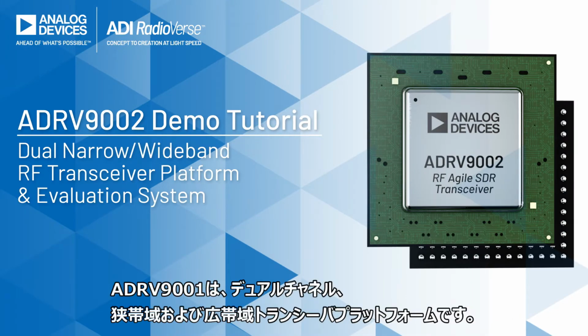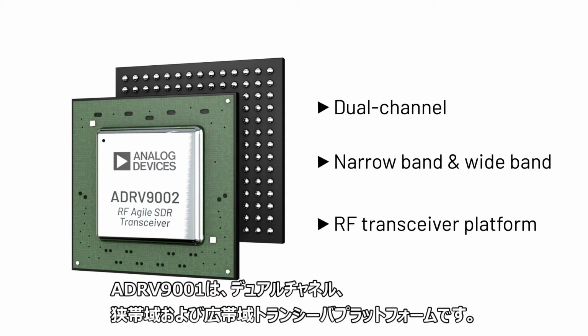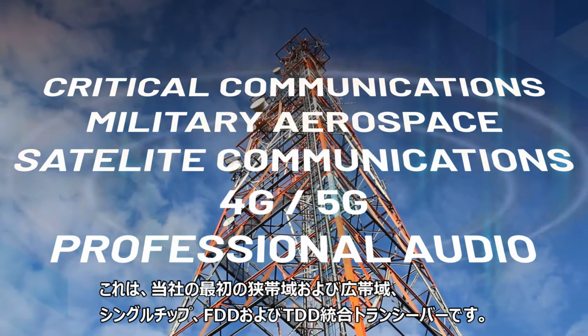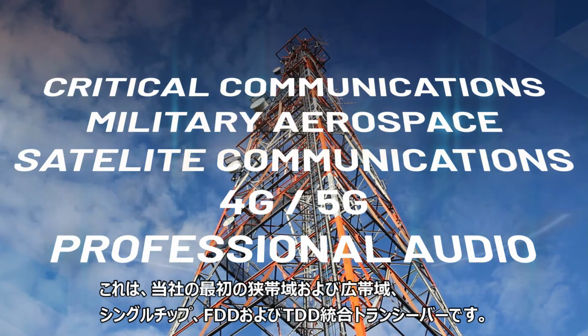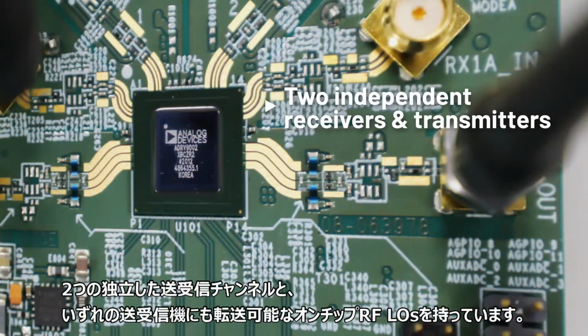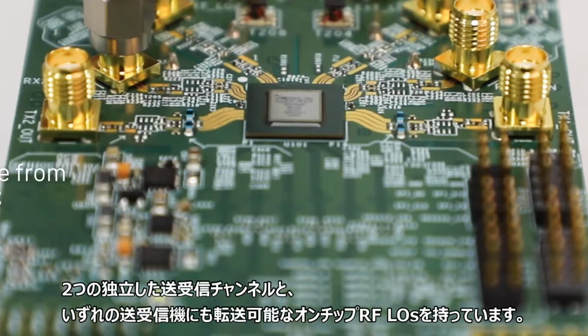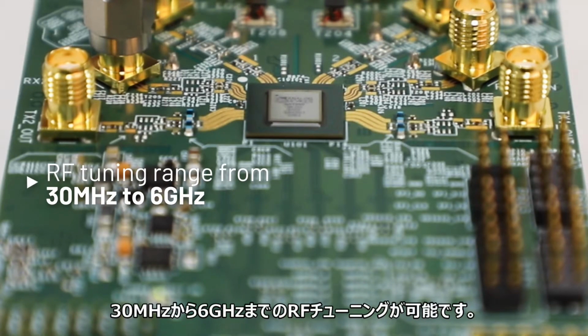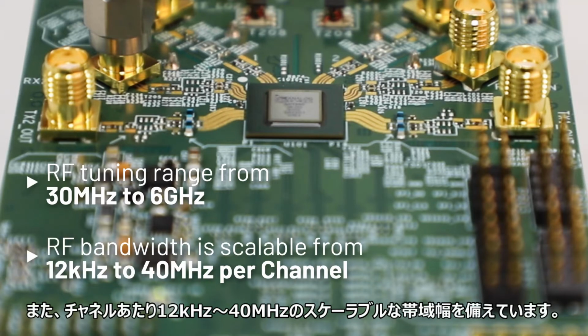The ADRV9002 is a dual-channel narrowband and wideband transceiver platform. It's our first narrowband and wideband single-chip FDD and TDD integrated transceiver. It has two independent receive and transmit channels and two independent on-chip RF that can be routed to any of the receivers or transmitters. It has an RF tuning range from 30 MHz to 6 GHz and has a scalable bandwidth of 12 kHz to 40 MHz per channel.